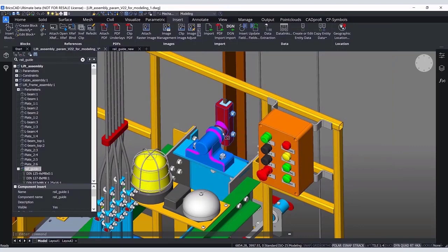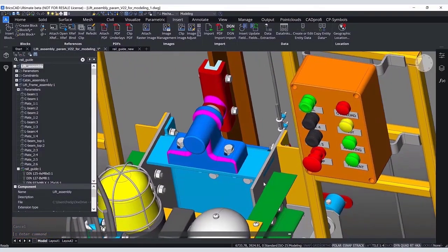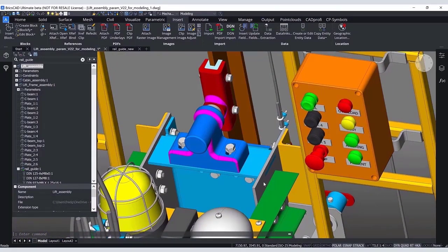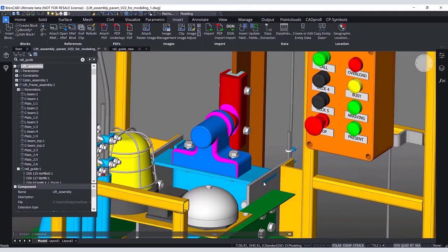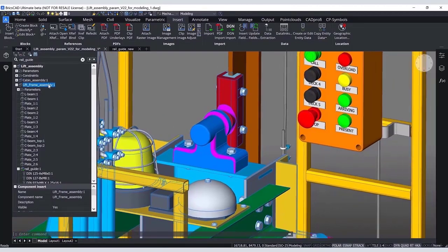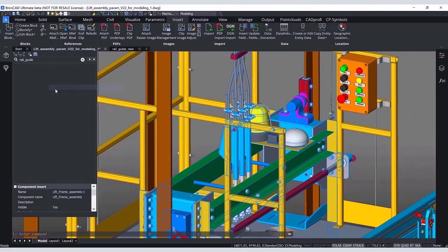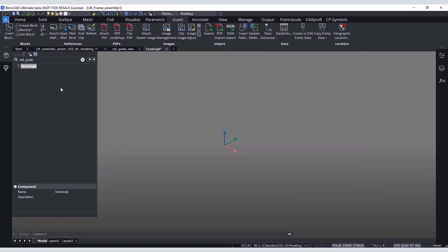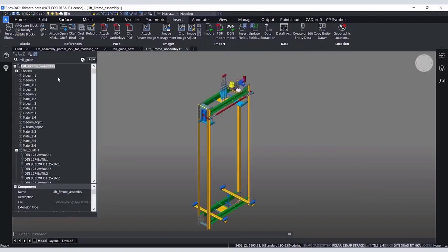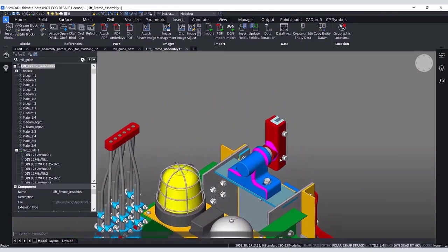Finally, we get to the last but not least feature, which we want to show you. In the previous version of BricsCAD, our intelligent copy-guided feature allowed you to easily and quickly copy 2D geometry to other similar locations. Now, in BricsCAD 22, the same powerful feature is available for 3D solids and blocks too. So I am glad to introduce to you the copy-guided 3D command.